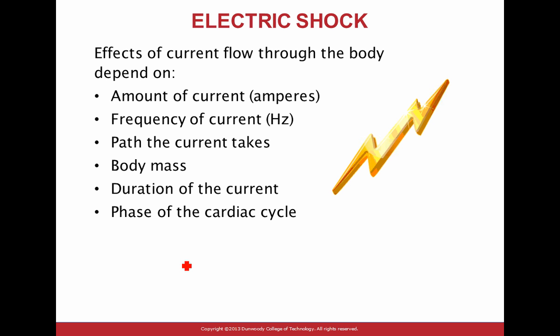They call it arc flash boundary, 4 feet, unless you calculate. And some transient happens in the panel, and the panel explodes, and you could die. All your insulated tools don't do you any good. So I always like to explain that one very clearly. Shock hazard is separate, almost completely, from the arc flash, arc blast hazard, that big ball of fire.